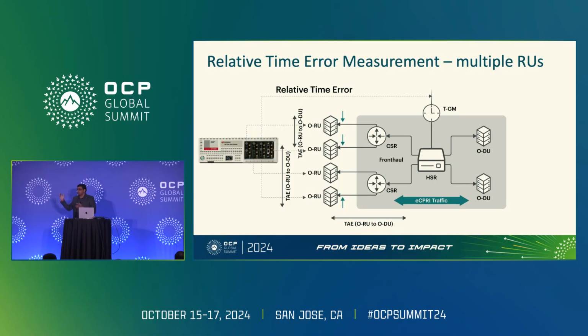So this network will have a lot of background traffic while it is propagating time using PTP, and as we know, there are always chances in an Ethernet based network that background traffic might impact a PTP packet, it might delay a PTP packet, and as a result there can be errors in how PTP calculates time.